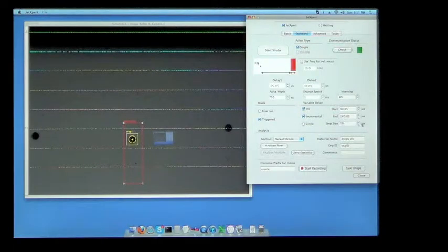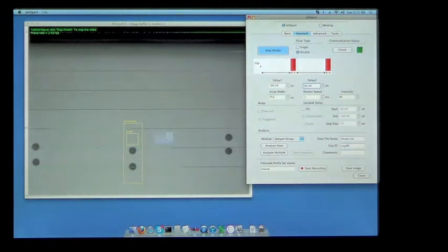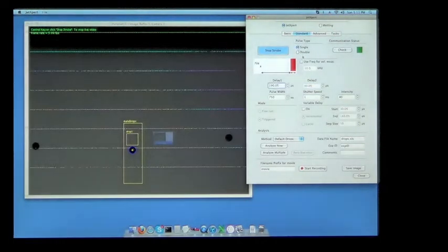Finally, it is possible to jet at such a high frequency that there simply isn't room to use a double strobe. That is, if the drops appear so frequently on the screen that the second image of one drop overlaps with the first image of another drop, it's important to use this mode here. Use frequency for velocity measurements.